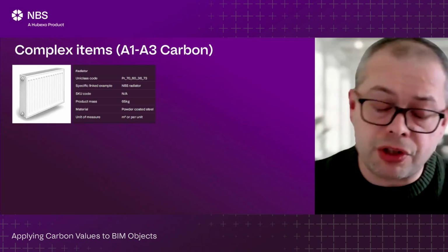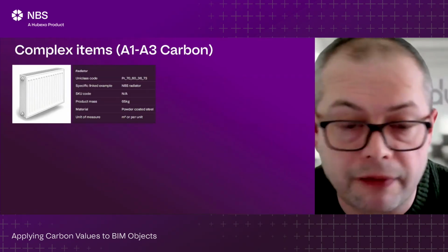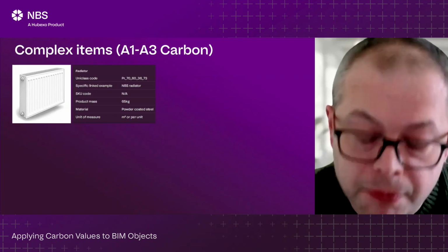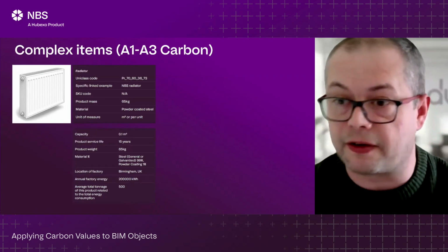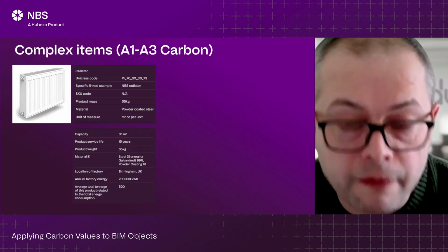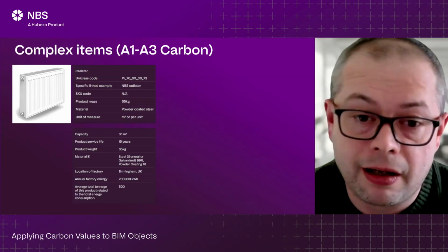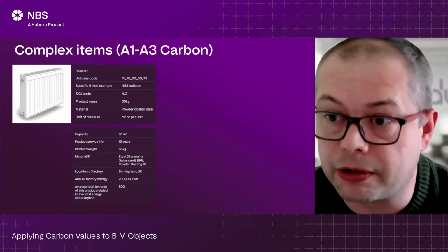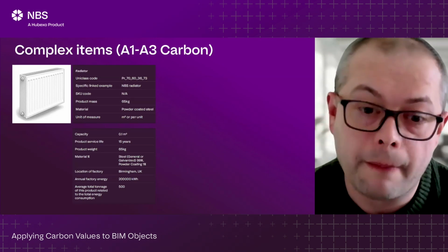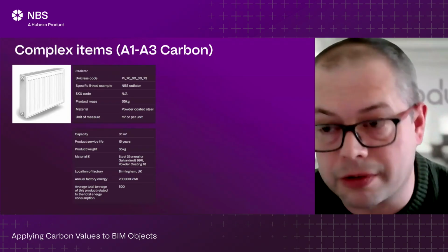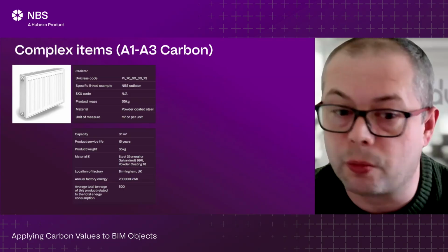Now, to do this, it is possible to use generic manufacturing uplift figures, which are available if you do a bit of a Google search. But possibly one of the most robust ways that you could do this would be to use the CIBSE TM65 embodied carbon methodology. This requires inputting some manufacturing information to achieve an A1, A2, and A3 breakdown figure. Obviously, for a generic product, you're not necessarily going to know what that is. But if you can estimate this, there's a whole host of information available online. You could quite easily find some figures that would suit what you're going to do.